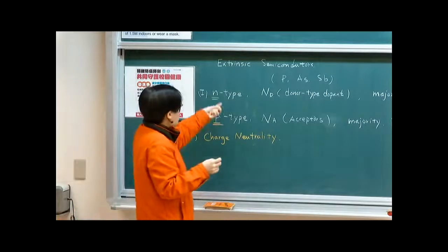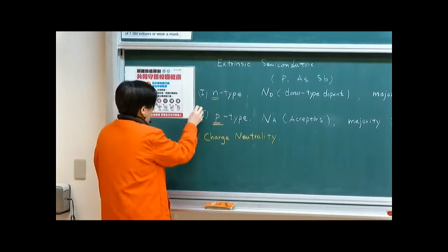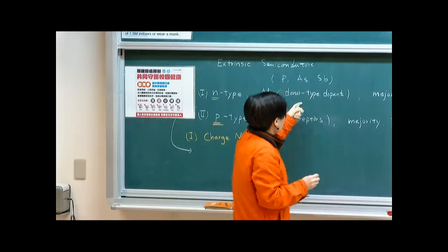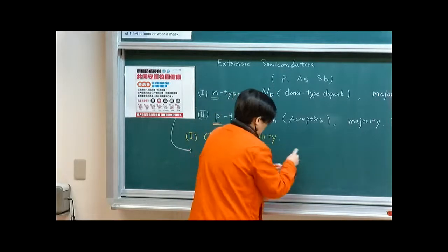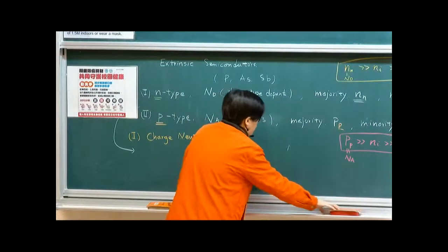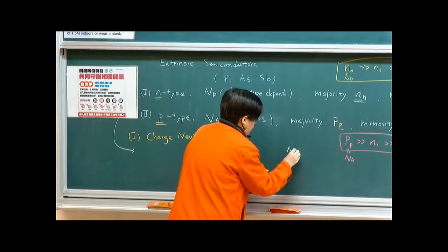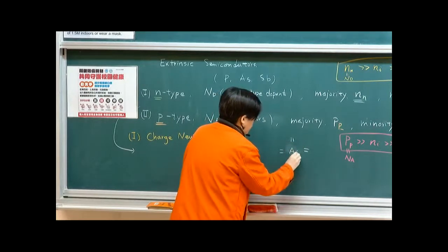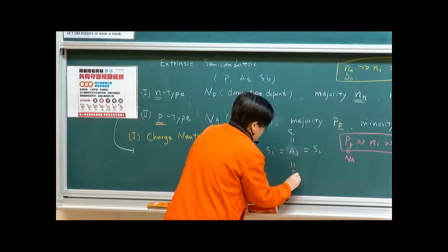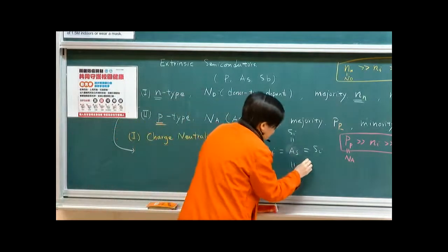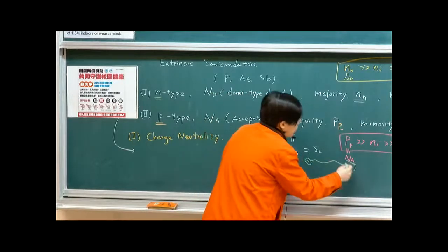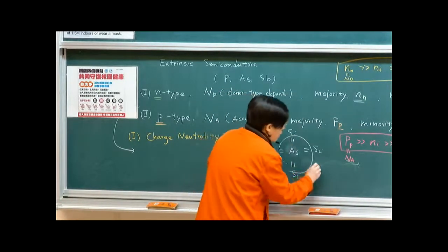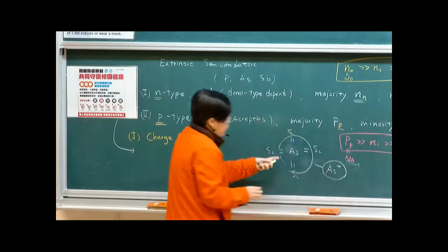Let's think about what happens in an n-type semiconductor. What is your positive charge? The positive charge is the dopant, N_D. Let's say this is my dopant. If I have a donor type dopant inside, let me use arsenic in silicon. If it has one more electron right here, and it donates it, the electron goes somewhere else. So if this electron left, this arsenic becomes a positively charged arsenic, As+, because one electron left it.